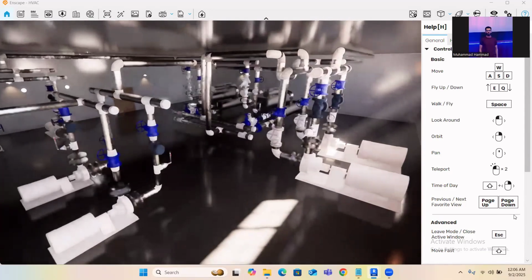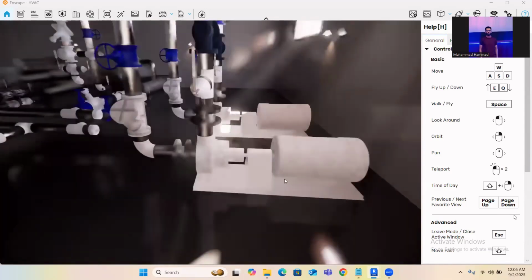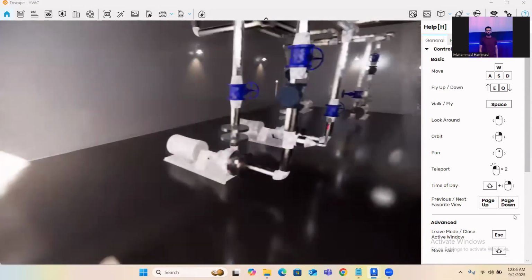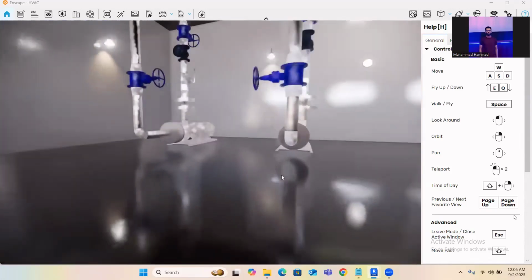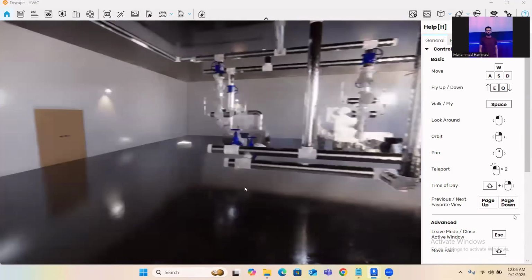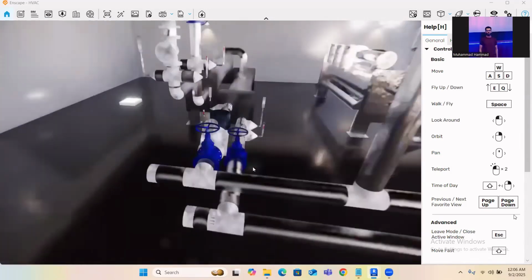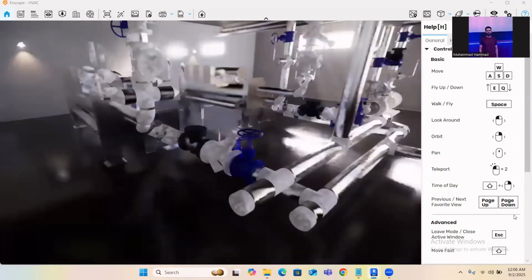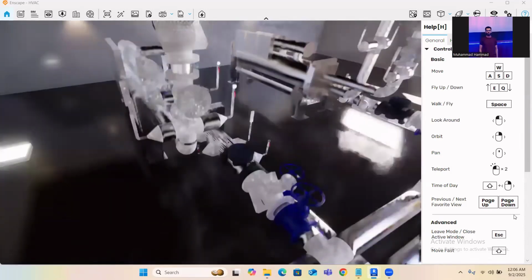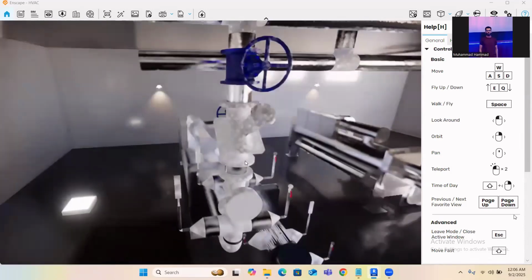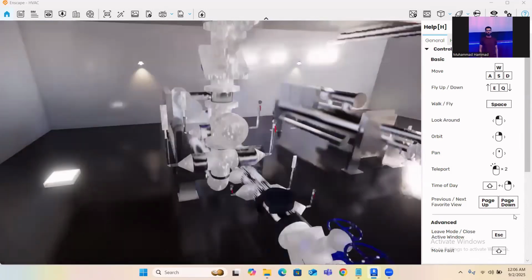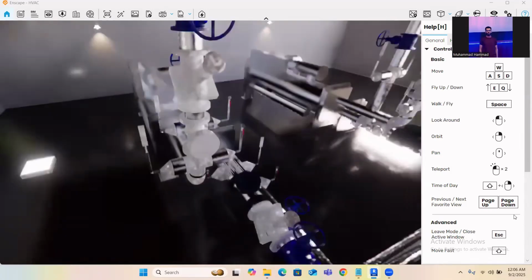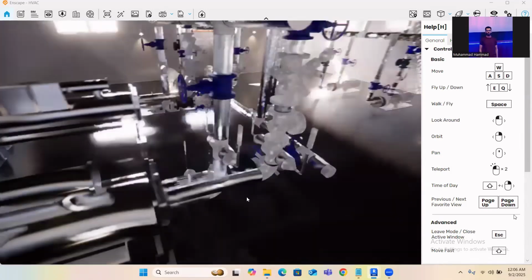So here we have these condenser pumps, and there is the secondary pump, and then here is the primary pumping system, and there we have got these screw type chillers and all the valve assembly attached to it, and all the gauges like pressure gauge and temperature gauges, and this balancing valve, gate valve, strainers, check valves.